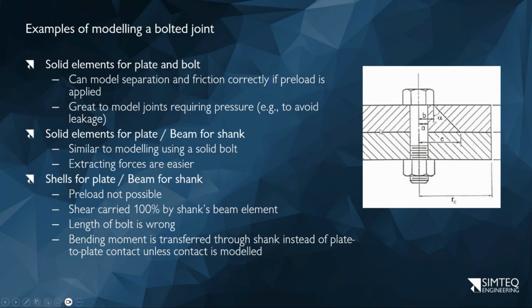So that's it. The next one is, you then typically use a beam element or a rigid, even if you really want to go that far, to connect the mid-surface of that one to the mid-surface of this one. And again, we have the choice of connecting directly to a node on the surface, or rather to an area which represents the area where the bolt is. Node-to-node connection is usable for certain kinds of structure. In general, it's preferred to rather distribute the load over a larger area. Otherwise, you end up with a pretty insane stress concentration that doesn't really exist.